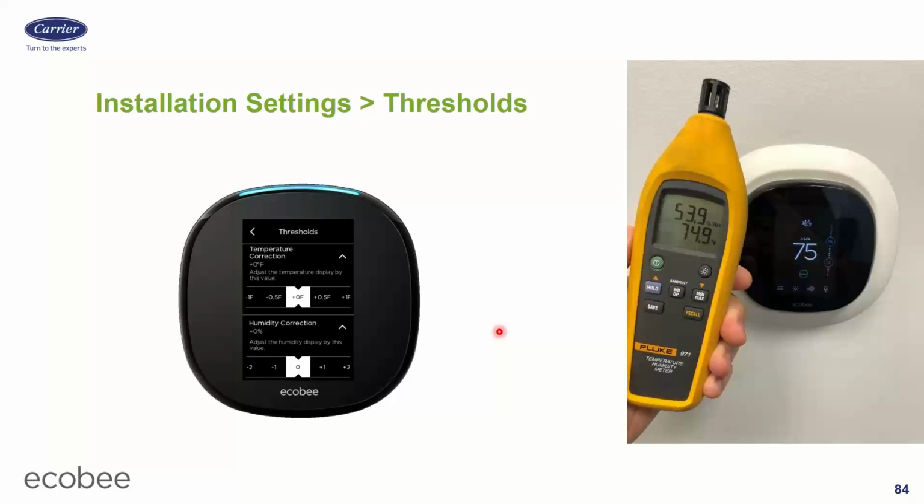If they're not accurate, before you start changing them, the first thing I want you to do is make sure there's nothing going on behind that wall. It is super, super common for there to be an open plenum type wall that air is moving through. Now, this might not even be an open airflow path for return air on your furnace. It could just be an open airflow path in the house in general because the house is not sealed very well. And cold air will move through there.